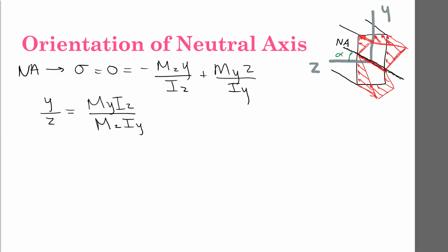So when we apply bending, which maybe is from a moment or some kind of transverse loads, the stress that causes in the member is an axial tension combined with an axial compression. So portions of the member are being pulled in tension along the axis, portions are being pushed in compression along the axis. We often refer to it as bending stress, but that really just means the normal stress, the axial normal stress due to bending, so due to transverse loads.